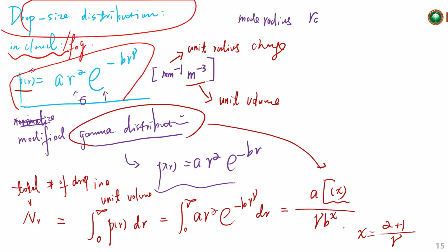So mostly we will use these expressions, even though the calculations are time consuming and it's difficult to get the exact drop size distributions, but it can offer us much more accurate results, because we can obtain the absorption coefficients, and we can also obtain the scattering losses. But for the ITU models, we can only get the total extinction attenuations. We cannot separate the absorption and the scattering losses.